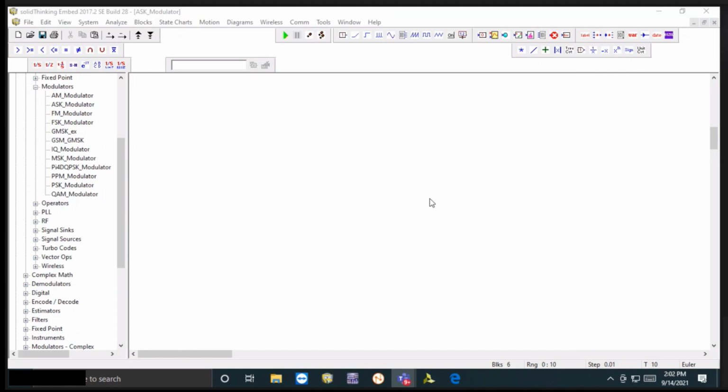There we have ASK, FSK, PSK, then QPSK, and QAM. Now QAM is for both analog and digital, so I'm not talking about that one today. I'm just talking about ASK, FSK, PSK, QPSK. QFSK is also there. All those are digital modulation. Here, your message signal is digital in nature. This is very special. The message signal is digital in nature, but the carrier signal is a continuous wave, high frequency sinusoidal signal.